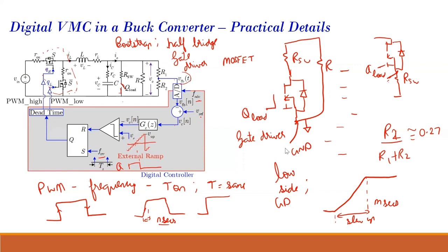So that's why we use this sort of arrangement to bring about what is known as a load transient. So what actually is a load transient? It is a sort of disturbance we are giving. And when the disturbance occurs, we want to make sure that this output voltage remains the same, because this converter is basically a voltage regulator.